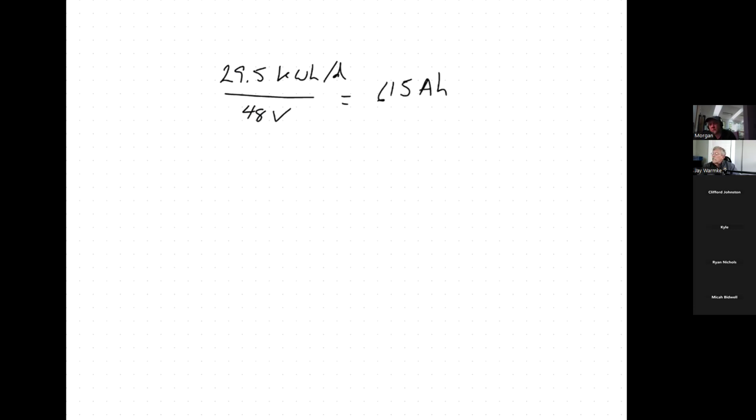All right, so this is going to be a huge battery bank, by the way, because you don't normally do battery backup for a whole suburban home like this. But let's say we're going to, because you're just interested in seeing how much this costs. So it would be 615 amp hours, 48 volt system, if we could use the whole battery and if the system were 100% efficient.